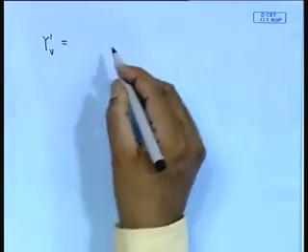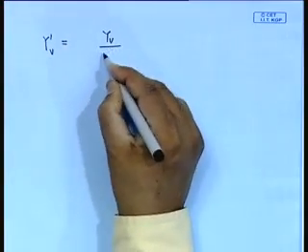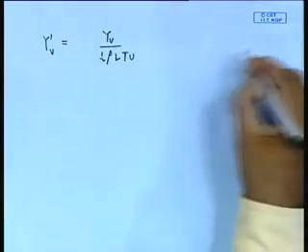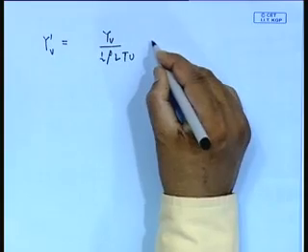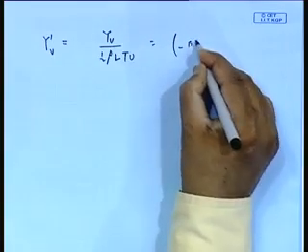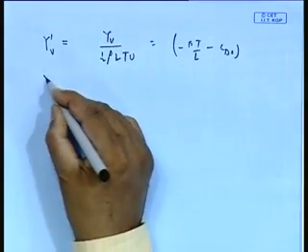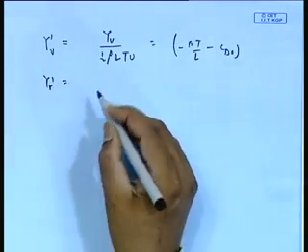Here the non-dimensionalization is done slightly differently. Half rho L T U. Actually, here the non-dimensionalization is done with that. I will come back to that. It is minus pi T by L minus C D 0. Then Y. In fact, the added masses are normally not.